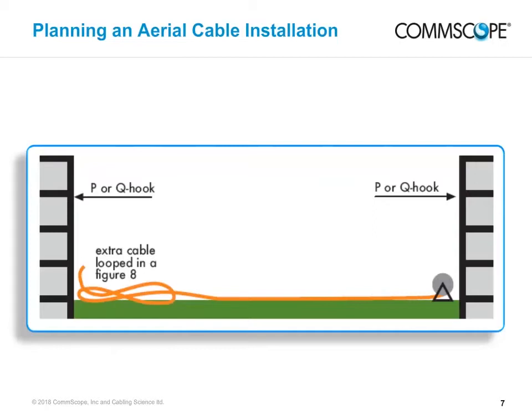Set up the cable reel beneath one hook and walk the cable end toward the second attachment point. Avoid kinking, scraping, or tangling the cable as it pays out from the reel. Block traffic from running over the cable. Once at the destination, continue to pull enough cable to cover the distance from the attachment point to the building entrance facility. Measure the distance carefully and include extra cable for the service loop.